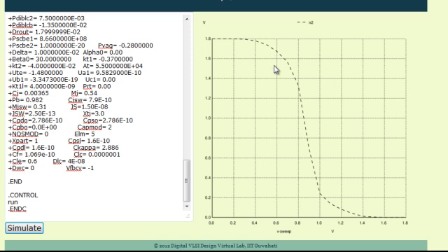In order to do that, first of all, we need to identify 2 points in this curve where the slope is -1, or -45 degrees with respect to the x-axis, which will come around here and the other here. By following the procedure we have listed in the theory section, one can evaluate the noise margin for the low state as well as the high state.